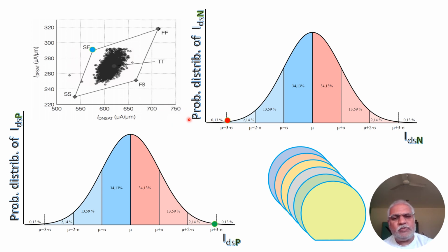To get to know how these wafers behave, models of these will be created, and that is called a process block. Based on that process block, the devices will have slightly different characteristics based upon their performance, and based on that, the corresponding design views are created. Since we are talking about the digital design, the standard cells are created. Those standard cell views are used in the design implementation.